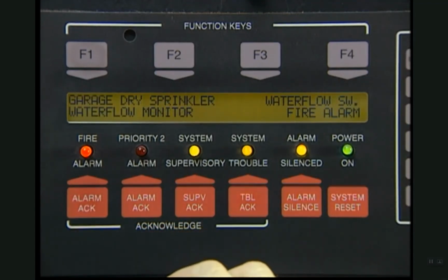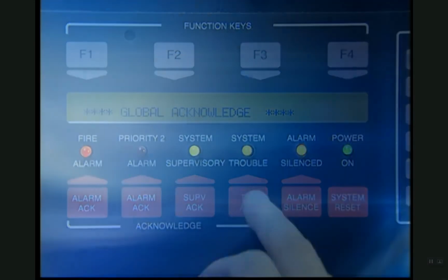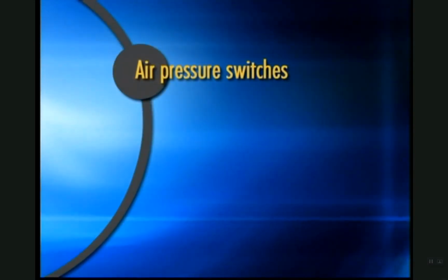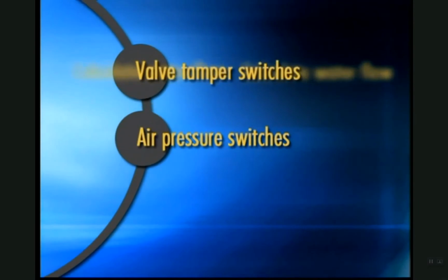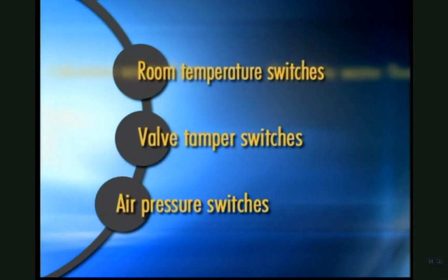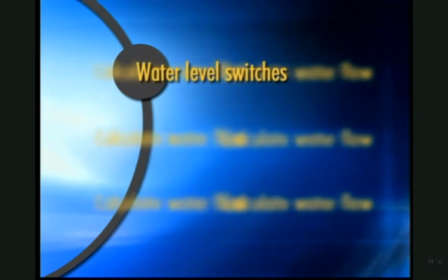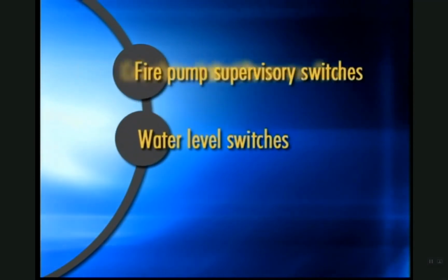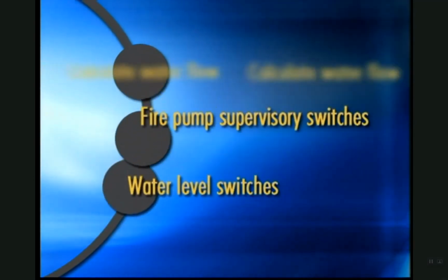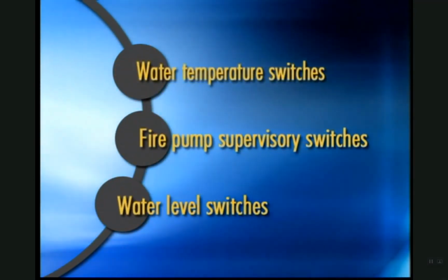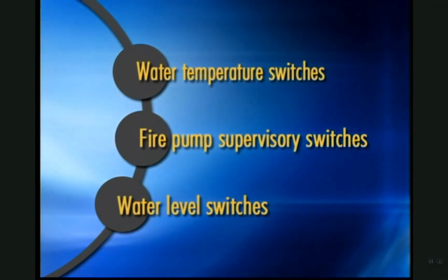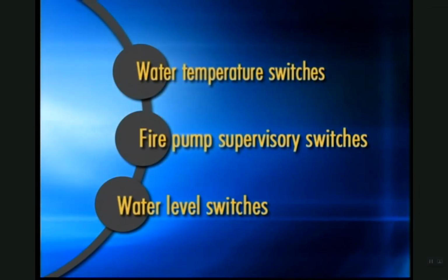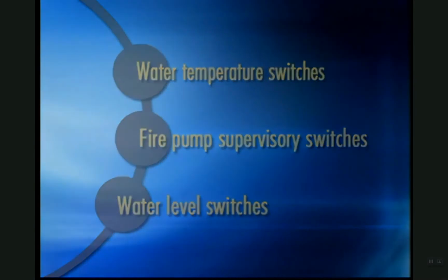Supervisory signal initiating devices should be tested quarterly. High or low air pressure switches, valve tamper switches, room temperature switches, water level switches, fire pump supervisory switches, and water temperature switches should be tested. Test criteria are found in NFPA 72.